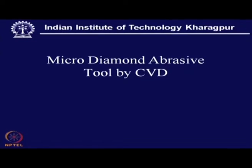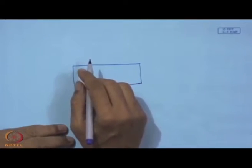Now, what we like to have is a micro diamond abrasive tool. So, we like to grow diamond in some discrete locations, not everywhere, some selected spots, and those selected spots can follow a pattern, some chosen array where the diamond will be nucleated and will keep on growing. That can be one of the innovative technologies, and it can be pursued just like the previous one, where it was more important to get the plastic bonded tape, that is the layer of braze alloy.